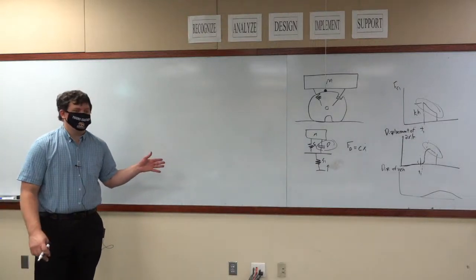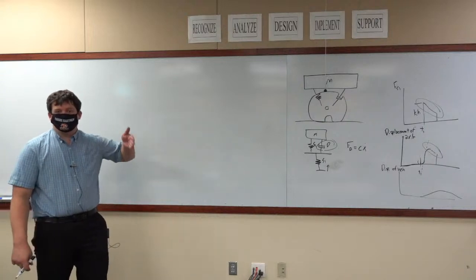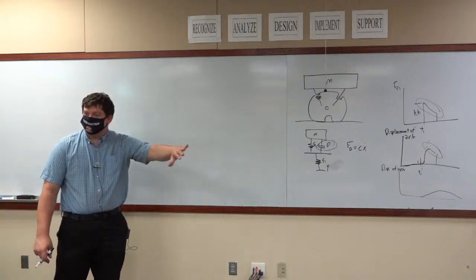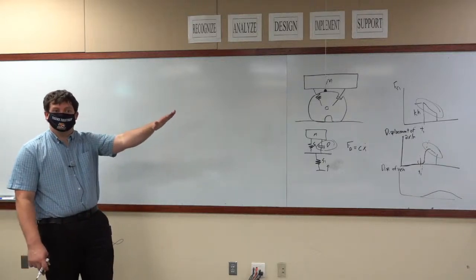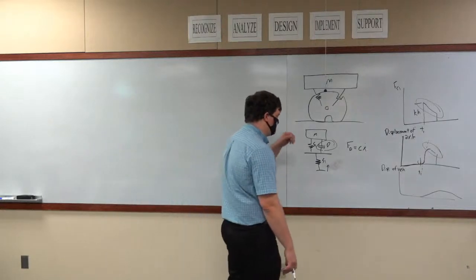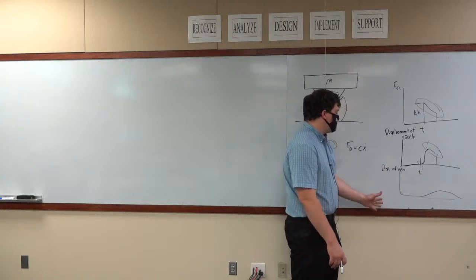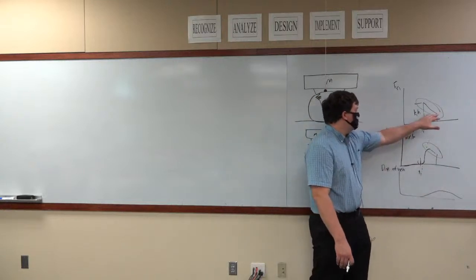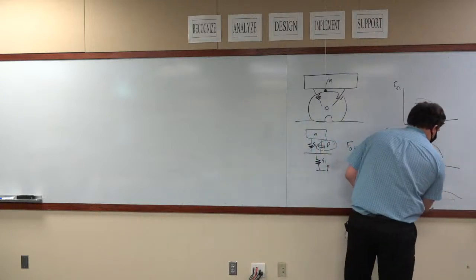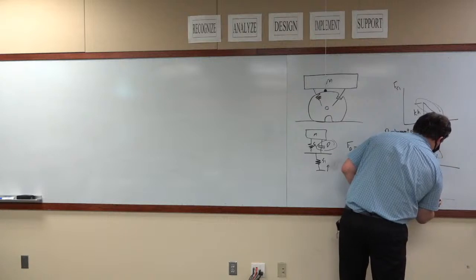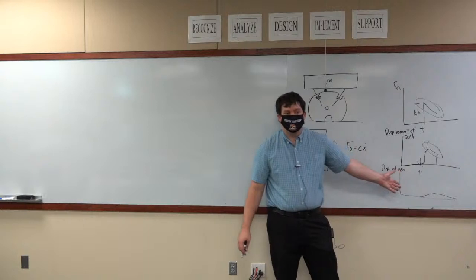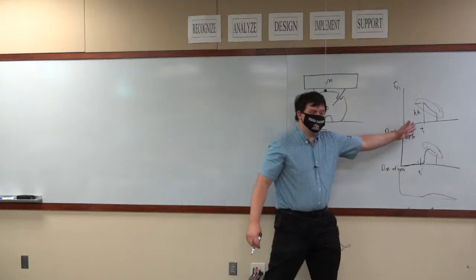This actually ends up being a filter. It filters out high frequency impacts, but it allows low frequency impacts to occur. Low frequency being like when you're hitting an incline and you're going up. High frequency when you're hitting a bump. So your suspension does act as a filter, and it prevents you from feeling this, but you do this instead, which even then, this is much smaller than that and much more gradual. That's comfortable. This is not comfortable.